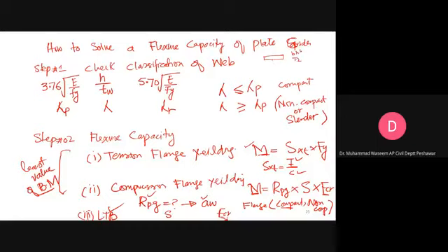Okay. Like you are saying that, okay, like this you can evaluate as I equals bh cube by 12. Okay. And for this is your I1, this is your I2, this should be bh cube by 12, and this should be bh cube by 12. This is I3, bh cube by 12. Basically, first we need this one, which is at the neutral axis. And simply it has neglected the moment of inertia of this portion and this portion.